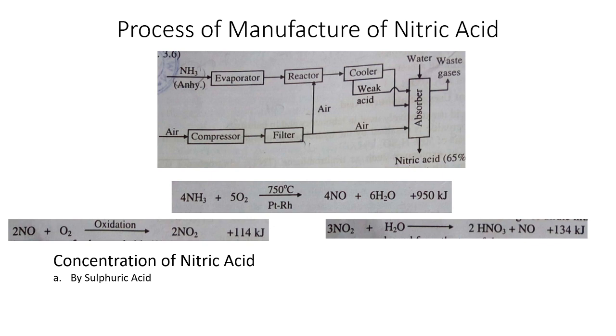So sulfuric acid itself gets diluted, and nitric acid gets concentrated. This nitric acid can be re-evaporated for the concentration purpose, or the 70% concentrated sulfuric acid can be used somewhere else if we need it. So sulfuric acid's property of dehydration is used here, and the concentrated sulfuric acid dehydrates nitric acid, making it concentrated. The output is 90% concentrated nitric acid. Okay, this is one method.